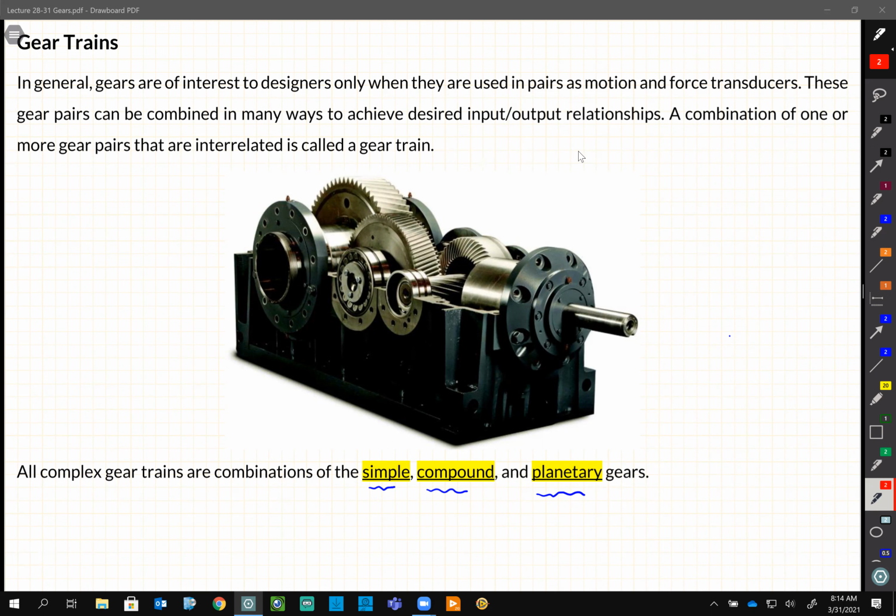So how cheap can you get a good metal 3D printer? It depends. There are 3 types that we have. One type uses powder, it's called SLS, selective laser sintering. They are in the range of $1 million, but you can print large parts and it does not require any support. It has a lot of waste though, because you have to use a lot of powder.